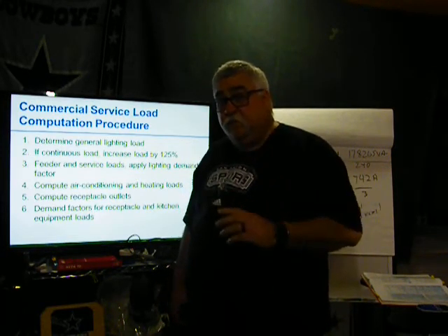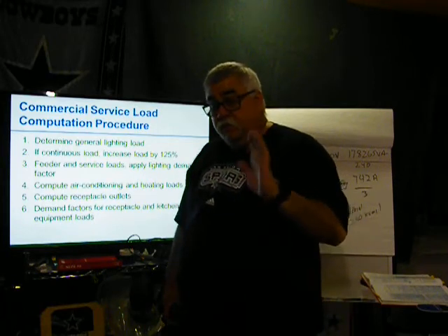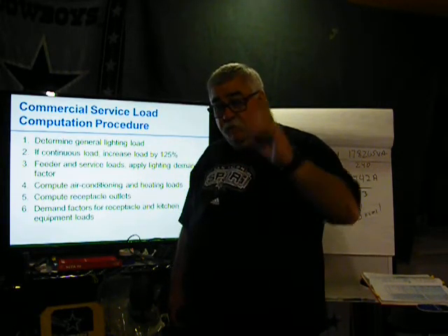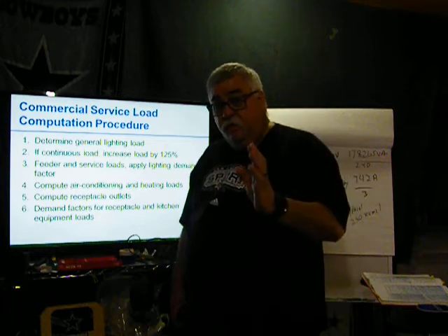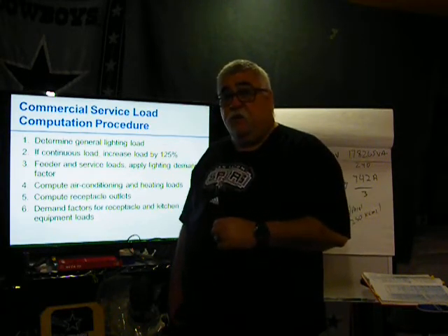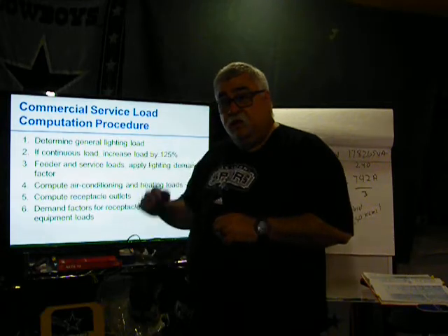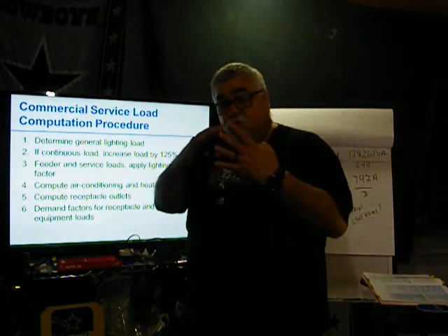So we're working on the same bank. Everything that I've given you is for the same bank. So we figured out the lighting. Now we figured out the power. Next step is figure out the feeder size and conduit. 4 wires: 2 hots, neutral, and the ground.